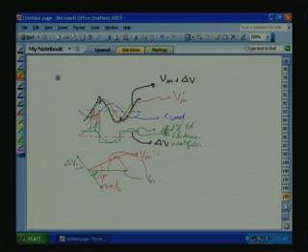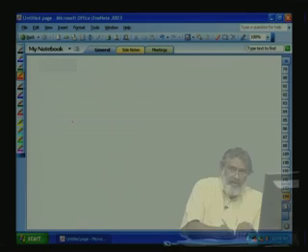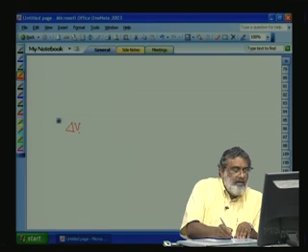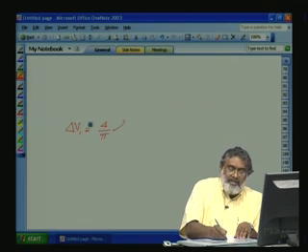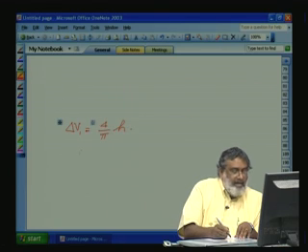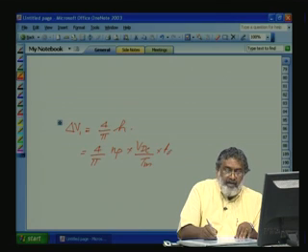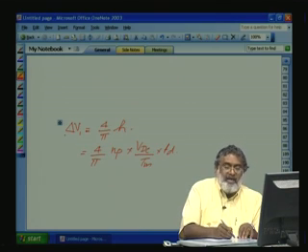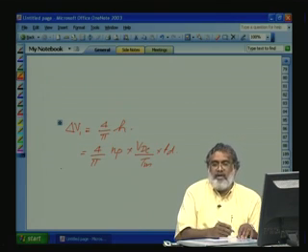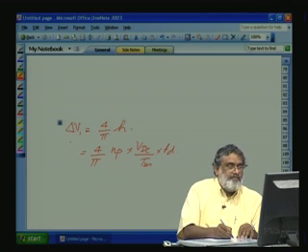So what it shows, the delta V1, we can say is 4 by pi into the height, that is equal to 4 by pi into Np into Vdc by Tm into Td. That is the fundamental of the equivalent square wave, rectangular wave.